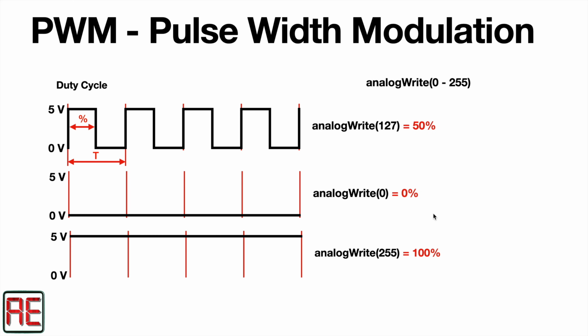The PWM outputs of the Arduino board varies according to the model of the board. For the Arduino Uno model, the PWM output can be accessed on pins 3, 5, 6, 9, 10, and 11, and the pulse frequency is 980 Hz for pins 5 and 6 and 490 Hz for the other pins.